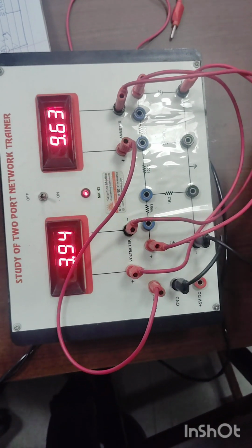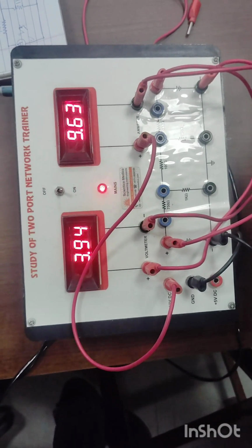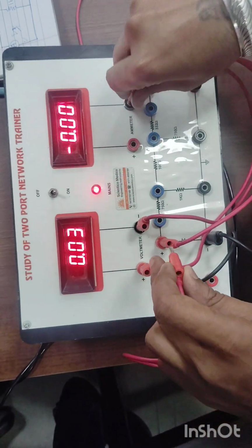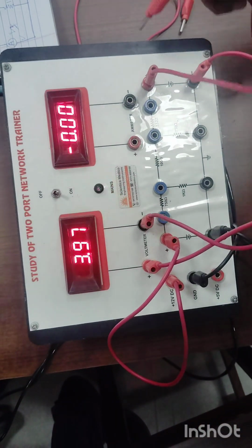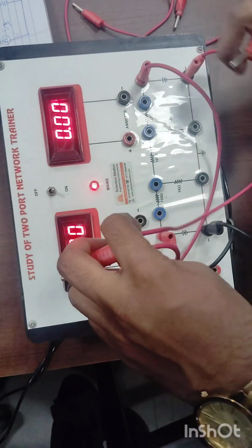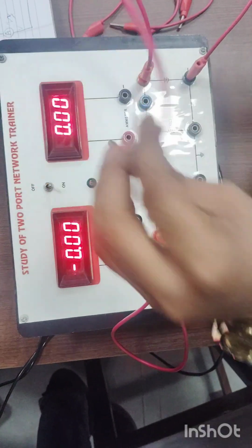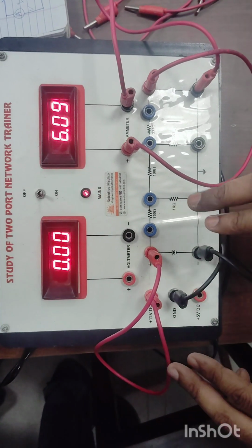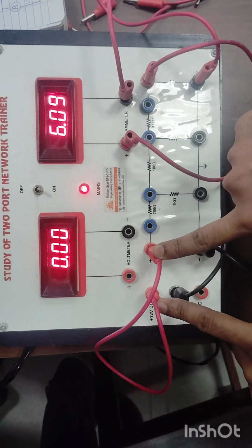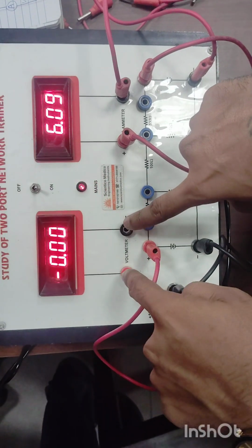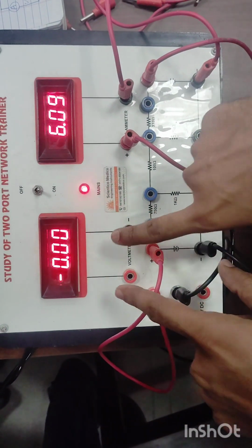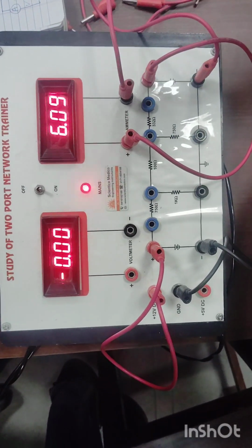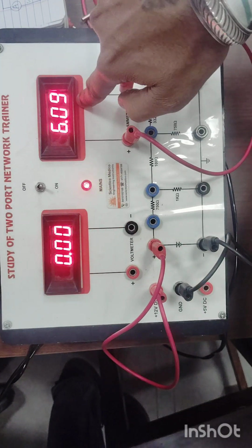Now we are going to case 2, where we need to connect the ammeter at the receiving end for measuring I2. I am connecting the power supply directly to the source here, and these two terminals are removed from the voltmeter and directly connected with the ammeter. And this is your I2. I am explaining again. First I am giving the 12 volt DC supply to the circuit and removing the voltmeter terminal of point AB from here and connecting it directly to the ammeter. So the ammeter is connected in series between points A and B, and this is your I2.